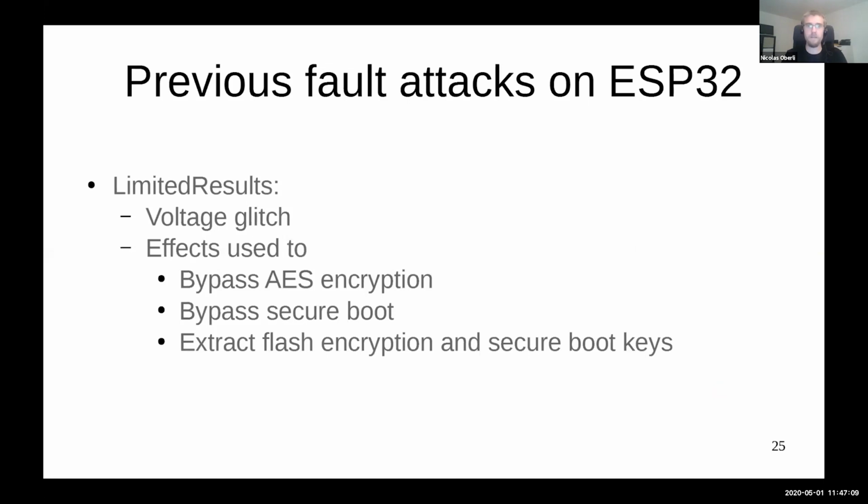There were previous fault attacks on this chip made by somebody called LimitedResults. He used voltage glitching and was able to get different achievements with this. For instance, bypassing the flash encryption, bypassing the secure boot, and even extracting the flash and the encryption keys directly from the device.